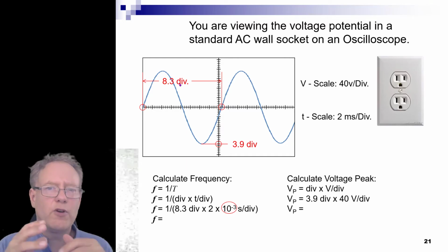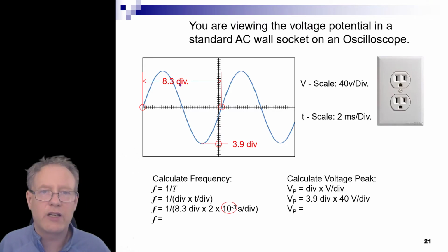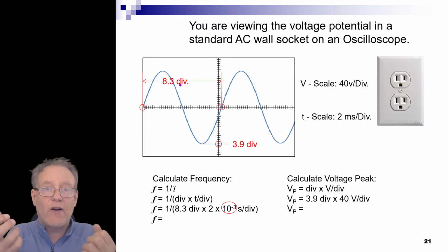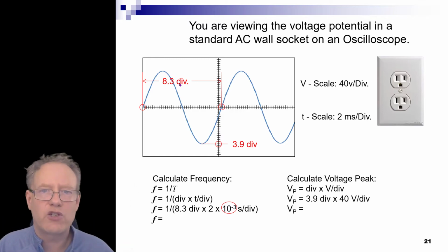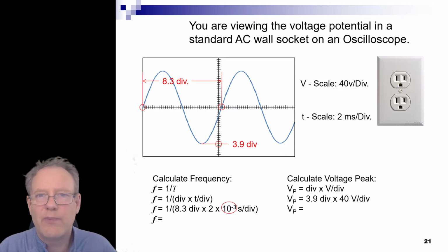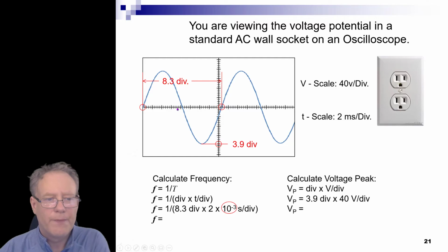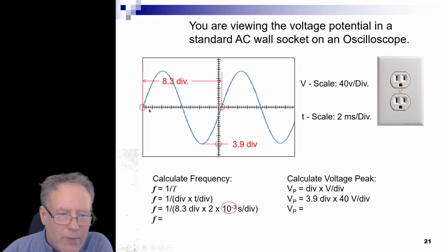Oscilloscopes will only give you a ballpark. They're not going to give you a really, really accurate reading, because it's a matter of how accurately you read the actual scale. Anyway, here we go. So it's ballparking at 8.3. Could be 8.32748, I don't know. It's 8.3, it's close enough. So there are 8.3 divisions in between here and here.